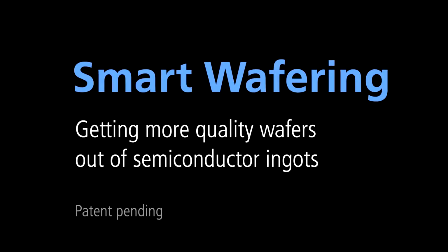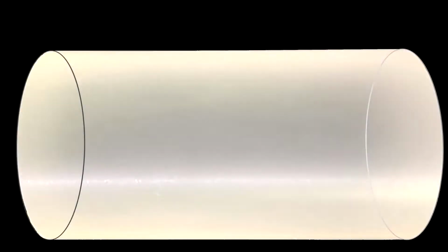I will explain the smart wafering approach that enables us to harvest more defect-free wafers from industrial crystals. When there are few defects in the processed core, their positioning to the cutting planes matter. Let us benefit from this effect. Knowing the precise defect coordinates allows calculating a core offset to position more defects into sawing gaps and out of future wafers. Let me illustrate the mechanism of such a gain with a simple animation.